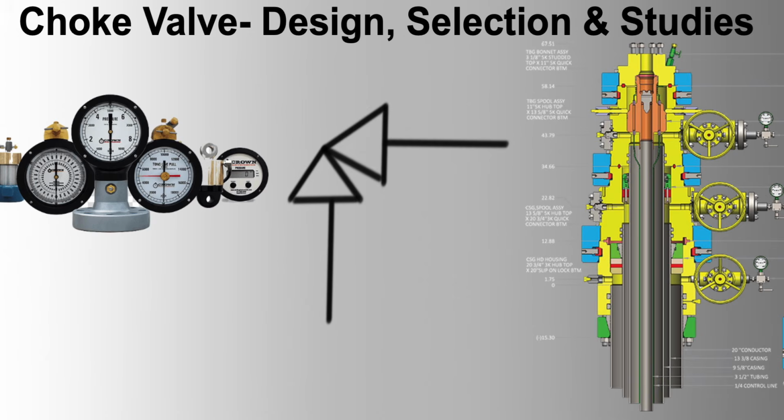Maintainability. 1. Modular design. Ease of disassembly. Modular components allow for quick disassembly, inspection, and replacement. Standardized parts. Using standardized parts reduces inventory complexity and downtime during maintenance.